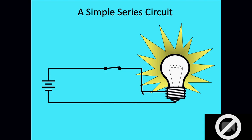What if somebody put a wire from there to there? What type of circuit is that? Closed. It's still going to be closed. Well, wait a sec. Electricity wants to take the path of least resistance, right? So what do I no longer have in the path that the electrons are going to take? You don't have a load. I don't have a load.